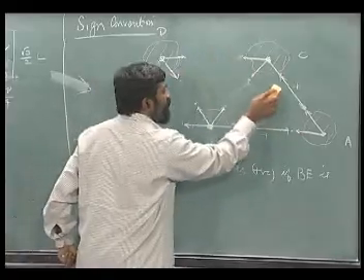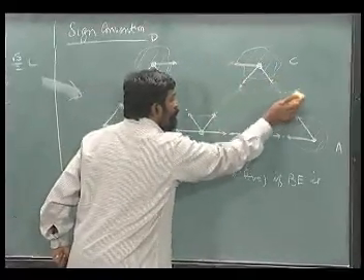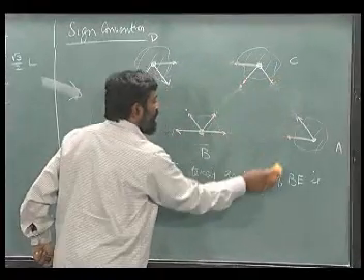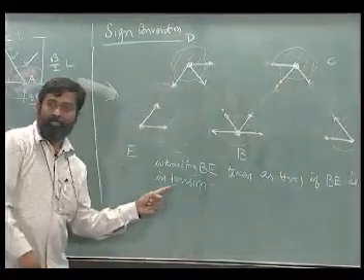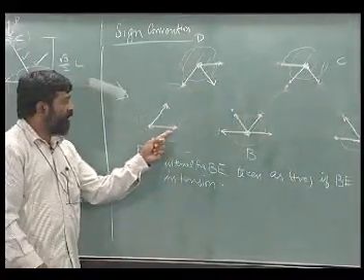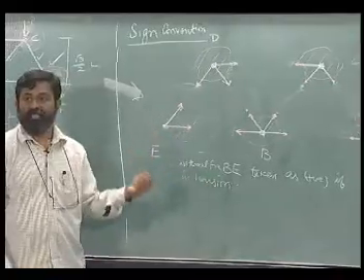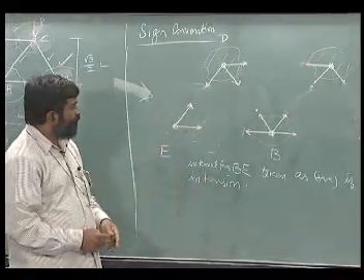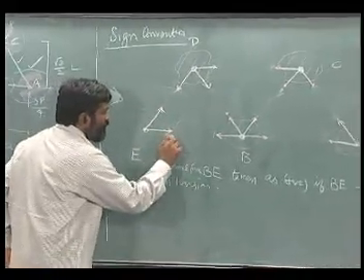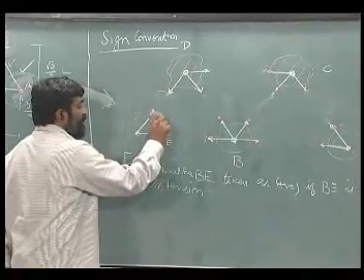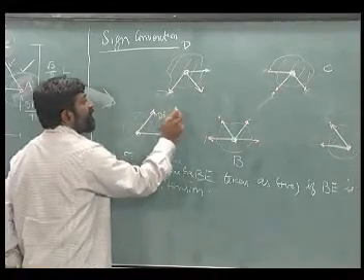The question is, how do I make sure I draw forces that indicate positive values? Okay. And if I get a negative value for this, it means that the member is in compression. Let me just write down the member forces here. This is B, this is D, and so on.